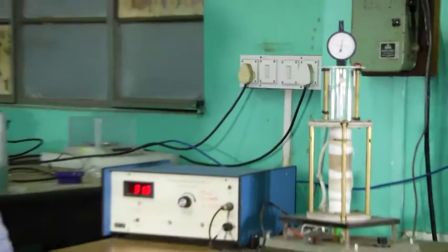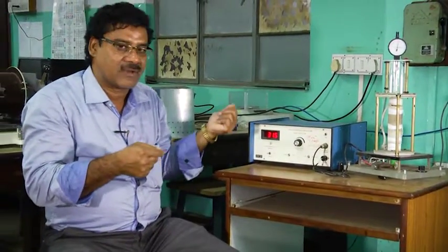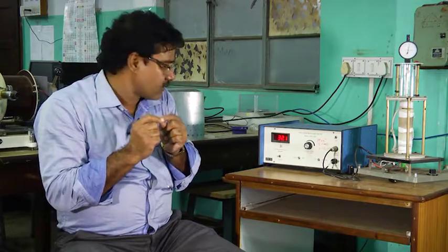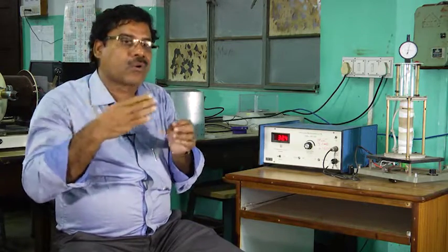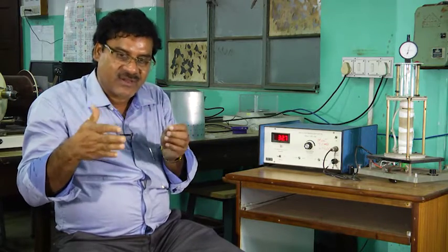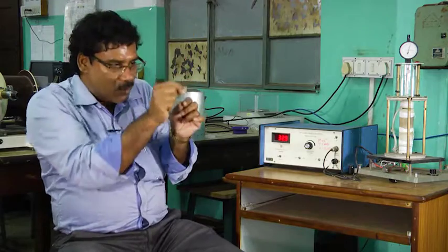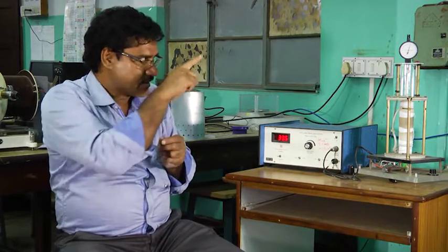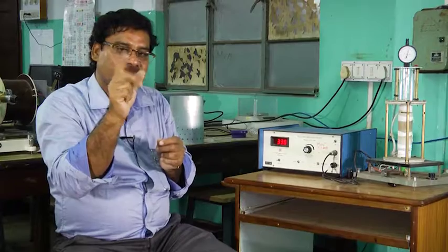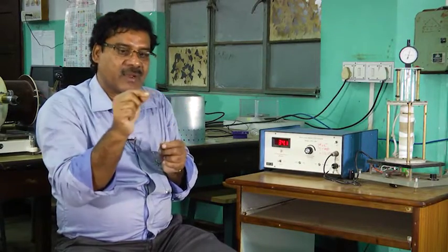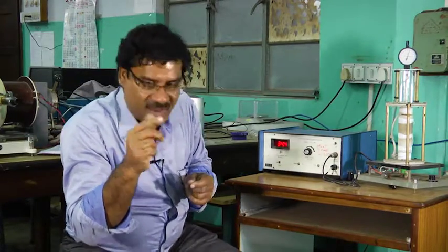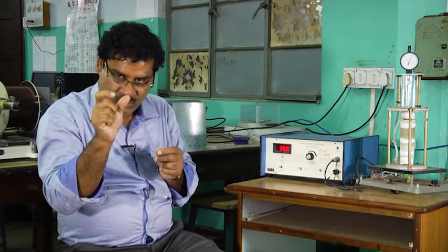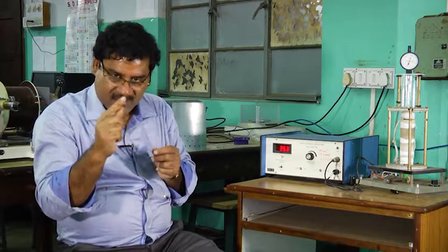So, at every 10 degrees, so initially it was 19.3, around 20. Then I took a reading at 30, then I will take a reading at 40, or you can take a reading at each 5 degree change of the temperature. Okay. So, I am noting down the temperature. Initially 19.3, then the micrometer reading was 0. Okay. Now, at 30 degrees the micrometer reading is 3 or 3.5, one can write approximately. Just you can guess between these two divisions, two lines. So, it was around the middle.